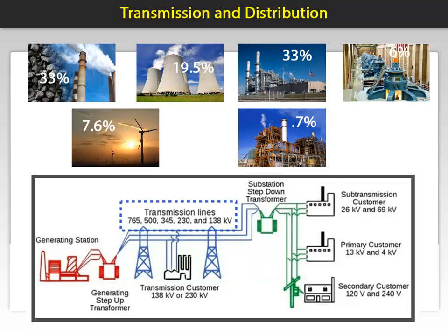Now, what is a transmission line? A transmission line is an aerial conductor that carries large amounts of electrical power at high voltages over long distances. You might hear engineers refer to these as high-tension lines. The transmission voltage level is determined by the required transmission distance as well as the amount of power carried. A larger transmission voltage is chosen when dealing with longer distances or larger transmitted power levels. As you can see, these voltages have a wide range.